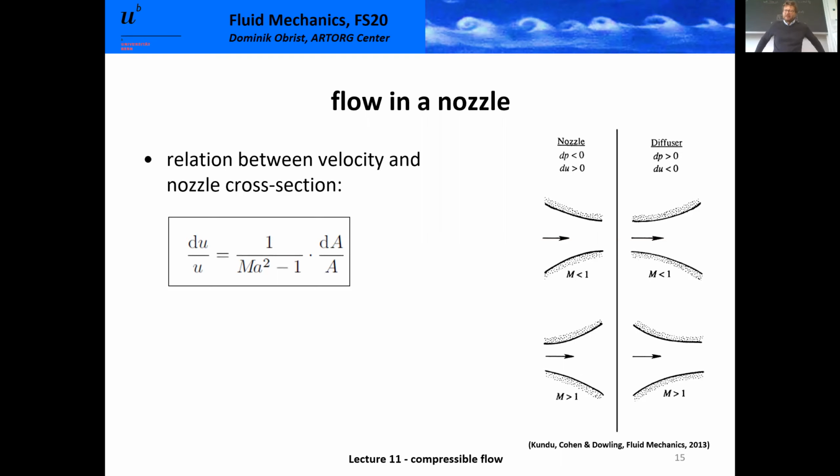What about the case when the Mach number is exactly 1? Well, when the Mach number is exactly 1, look at the formula here on the left-hand side. We get a 1 over 0, so that's not a very good thing. Maybe we put this term on the other side, so we multiply by Mach squared minus 1. So we see that for Mach equals 1, the left-hand side is multiplied by the factor 0, such that the Mach equals 1 case is only possible if